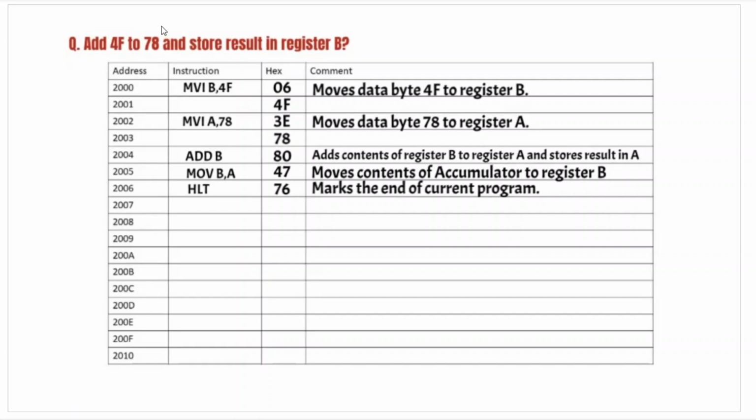Keep note of the memory address locations and the hex codes. What we'll be doing is entering the starting address, and then entering the hex codes. We have to enter only the starting address. The rest of the addresses will be incremented on their own.